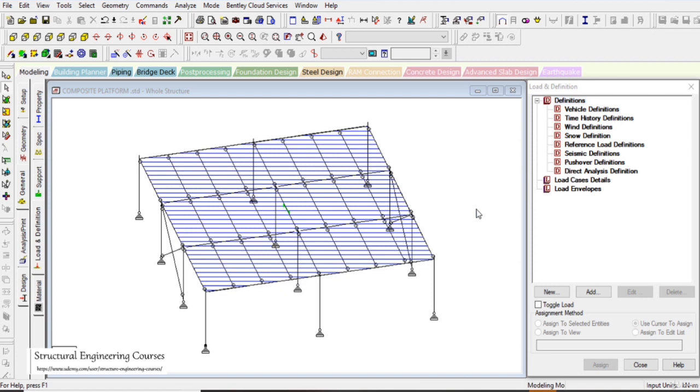is that for the steel structure there are various options for doing the design and analysis as per the American standards. But American standards are somewhat, I must say, complicated in the perspective they deal with the structures. So to make the design process simpler, we have a process called direct analysis. For steel structures, the direct analysis approach is most widely used, I must say, when we are designing the structure with the help of a STAAD software.